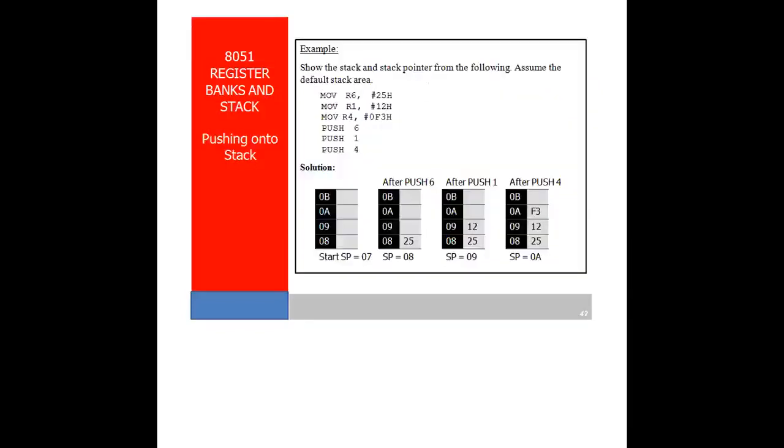Now let us take suitable examples to clarify it. Here is example one, and we have shown a sample program. From the following, we have to find the status of the stack and the stack pointer after executing these instructions. We have written the instruction MOV R6, #25H. It will load 25 inside register R6.